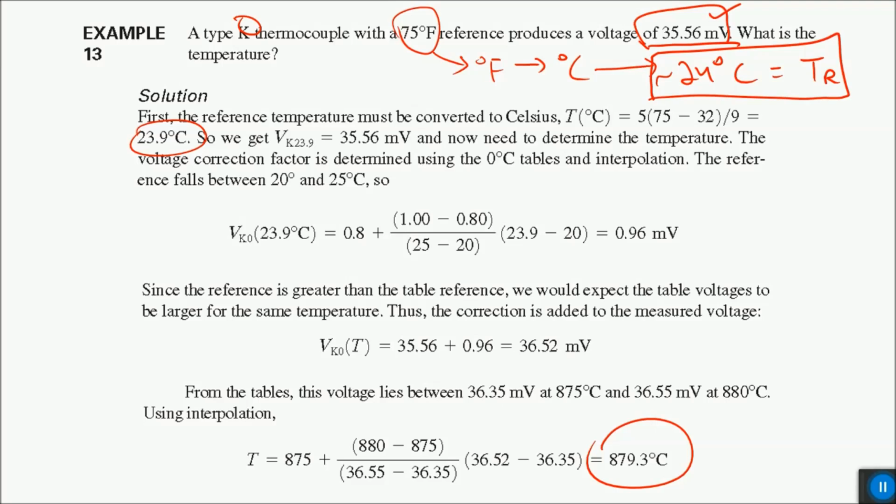So we have to be very careful. The mistake that is usually made by students while calculating these sorts of circuits is that instead of adding this, they subtract this. Actually, for the slope to shift down, we have to subtract this. But now your reference is already changed. So you have to find out what magnitude of delta T was producing this voltage. So you have to add it for calculation, because you are solving it in a reverse manner. So be very careful about that.